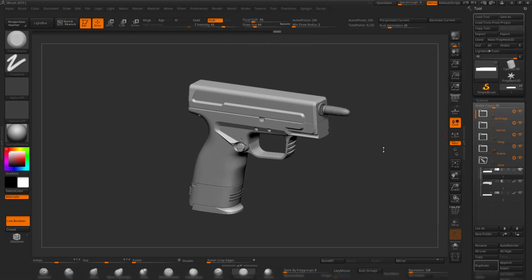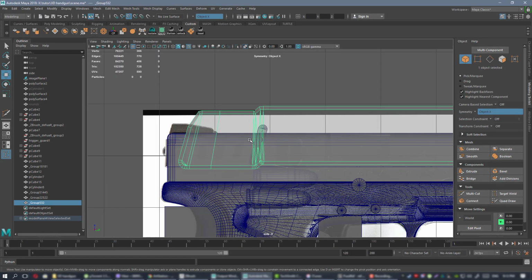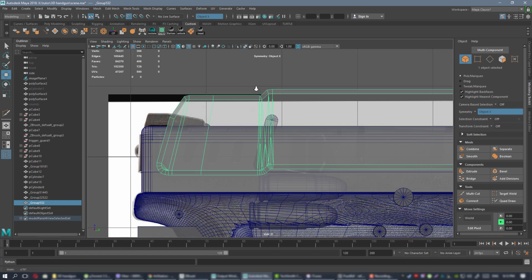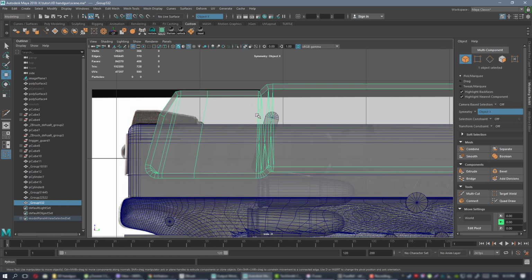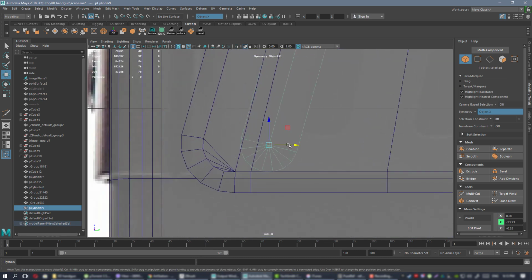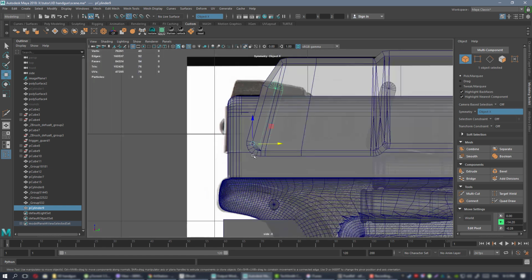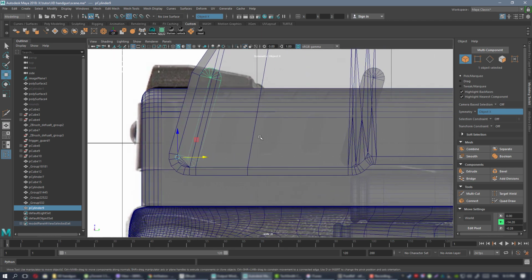So, about serrations, right? I already have this shape here. Yep, here it is. And let's hide. No, actually, I'm not going to hide. I'm going to set the last serration here. Just duplicate this cylinder and do the trick I did before. Snap two points, hold D to edit pivot, snap it to this point, and snap this guy to the corresponding point on the other shape, and here it's snapped perfectly.